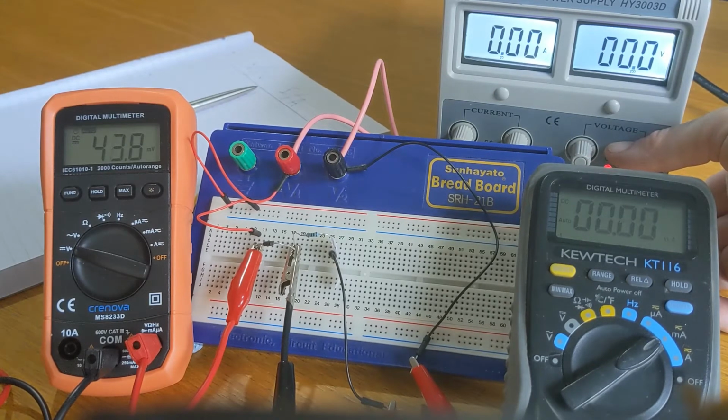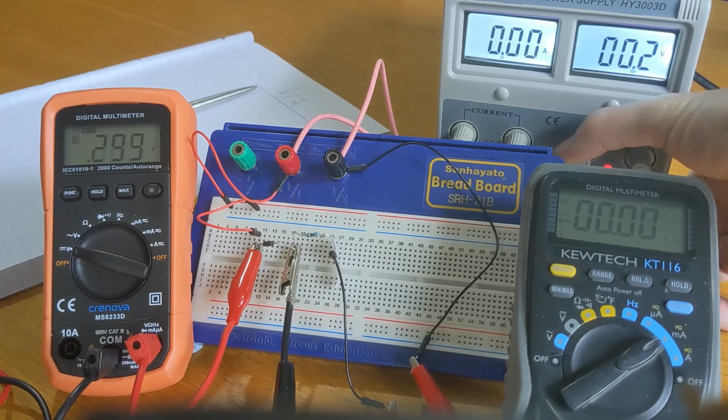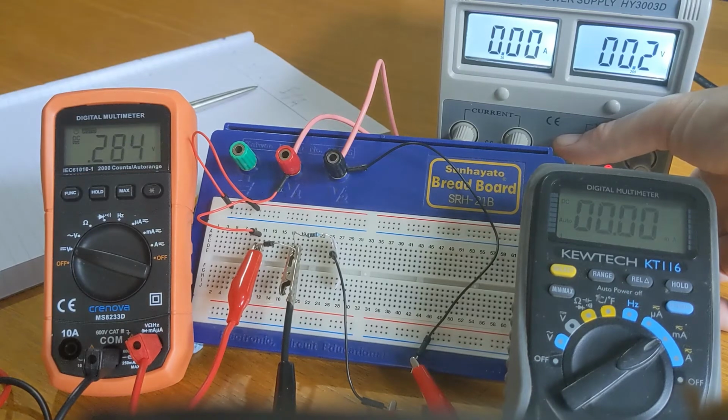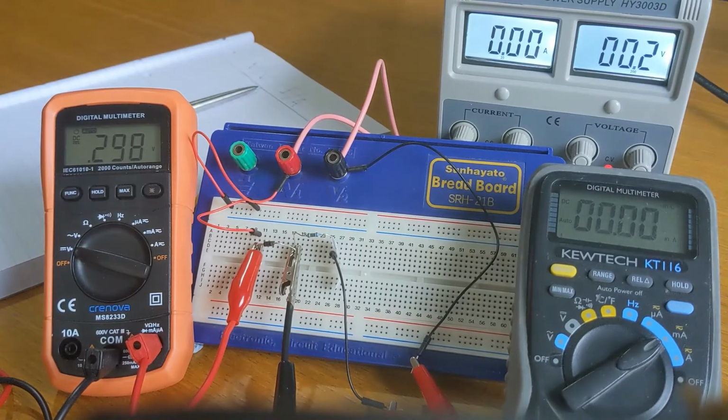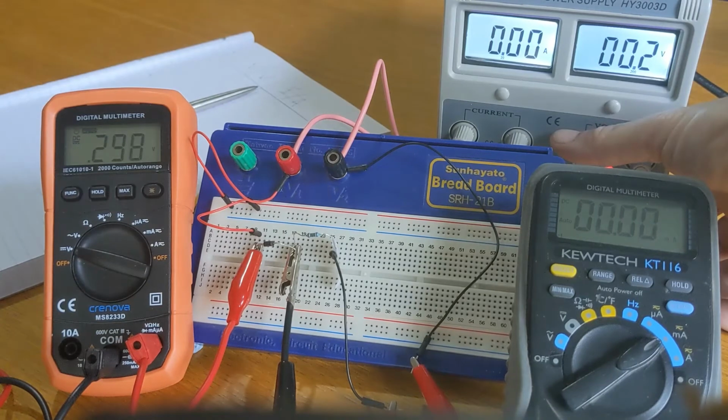Let's increase that a little bit, and let's try and read, let's say 0.3 of a volt, 300 millivolts. But you can still see at this stage, whatever readings we take from the voltmeter, that we have got 0 milliamps. So that's pretty close there to 0.3 volts, but still 0 milliamps. Again, make sure that you're taking whatever results you think are appropriate as the meters change.